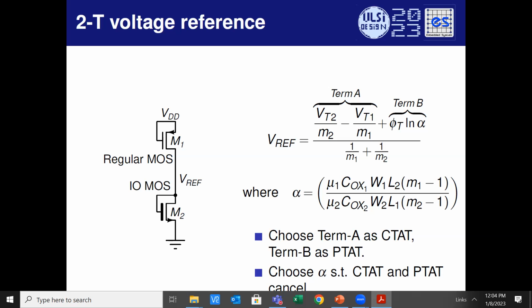Sir, when there is no VD, then the transistor is in off state, right? You told that in cutoff state there is a leakage. Gate and source are at equal voltage. Drain and source don't have to be at equal voltage. Okay, sir. There is some potential difference.